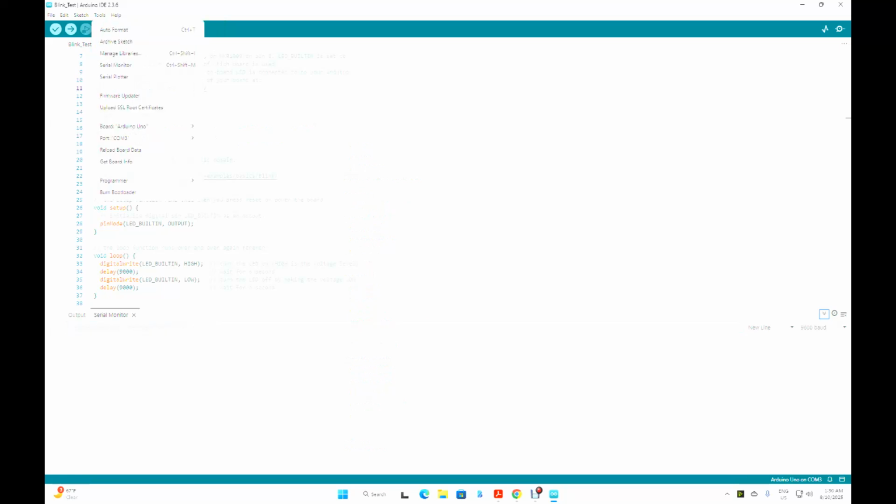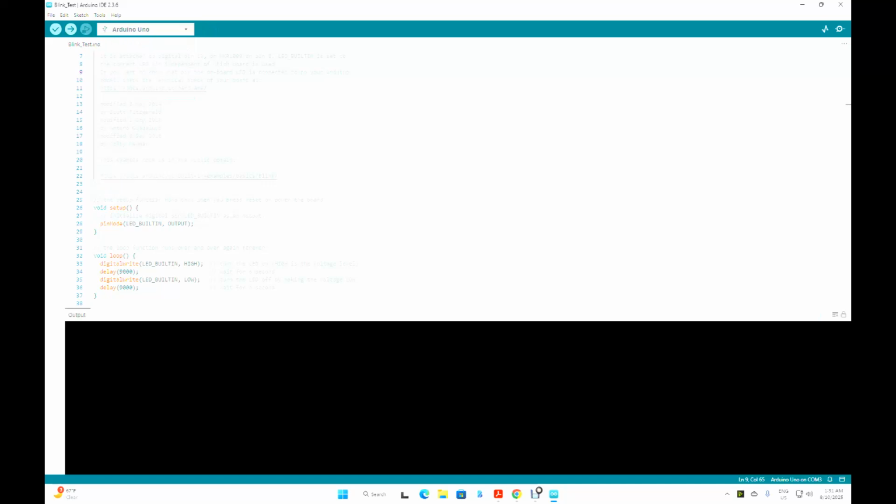Okay, the next thing you have to do is go to Serial Monitor. If it connects, that means that you have the right COM3 or COM5. On the bottom, it says Arduino Uno on COM3, so that means I believe it connected.